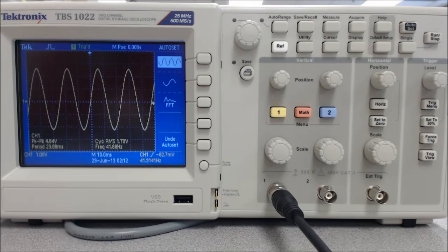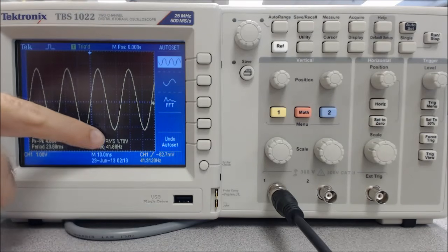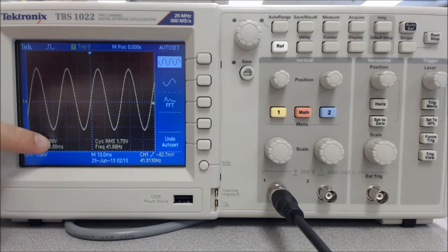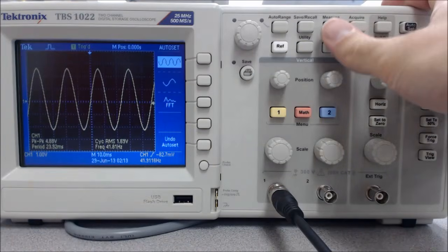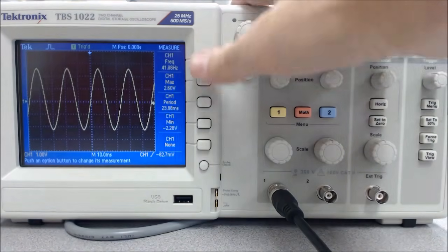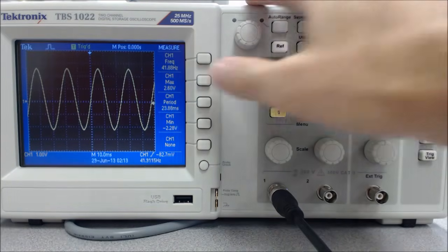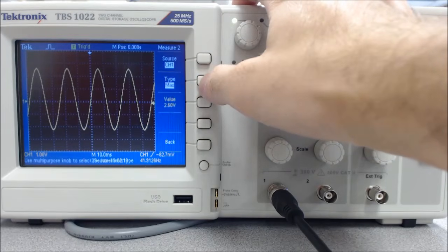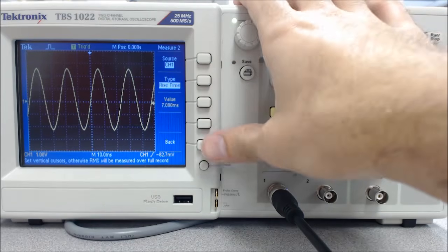Let's take a closer look at the oscilloscope, and I'll show you a couple of the buttons you'll want to know about. So first of all, let's take a look down here. You can see that the oscilloscope gives us some information about the frequency of the sine wave and the peak-to-peak voltage of the sine wave that we're seeing. Those come in handy pretty often. You also may want to take some measurements other than those off the sine wave. So you can see if I press the measure button, I have, for example, the maximum and the minimum. And you can change these measurements by pressing the button next to the measurement and changing the type.